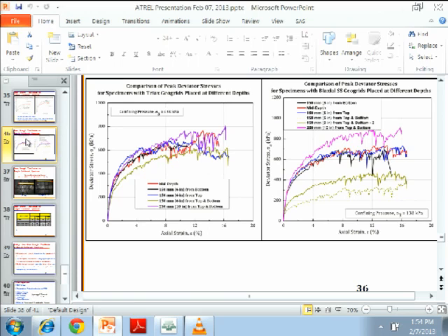Yeah, if I can, Professor Hessler, I can add one more thing. 30 seconds. Okay. What we are applying here is just a repeated pulsing load, but what the ballast layer in the field is going to see is all the vibrations coming from the train. And we just have a cylindrical sample in a membrane, confined, whereas in the ballast layer there is a lot of other room. It's almost like something jackhammering the rail, and there is a lot of movement of the material that can migrate away from the ties, which people have seen. So that is when the geogrid comes into the picture. At least it prevents the migration, which may not be reflected in a repeated load triaxial test, but the application really holds the material together, and then it improves its performance.